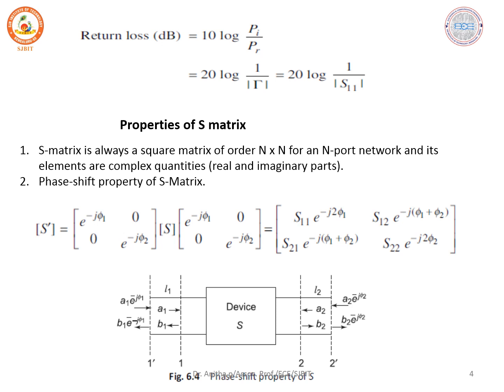Even this is expressed in terms of decibels, and it is defined as the ratio of incident power to the reflected power. 10 watts I had given, reflected power we got as 3 watts, 10 by 3. So that gives you the return loss.